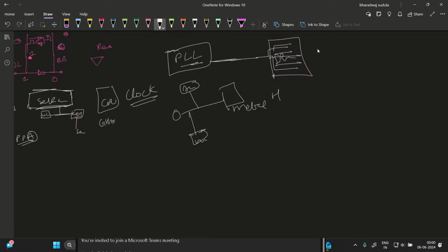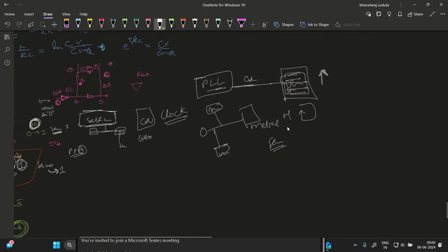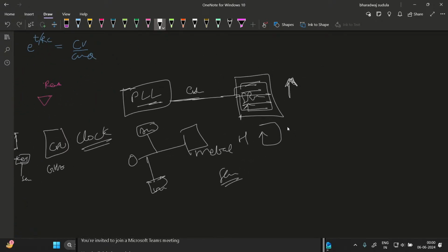SRAM actually works even at higher frequencies than the clock that is being generated externally. We can access SRAM at a really fast pace. So it would be better if we could generate an internal clock within this SRAM itself, so that by itself it can generate some control signals like sense enable. All this is happening right now in the industry. They are generating self-timing circuits. Yes, self timing circuit is everything.